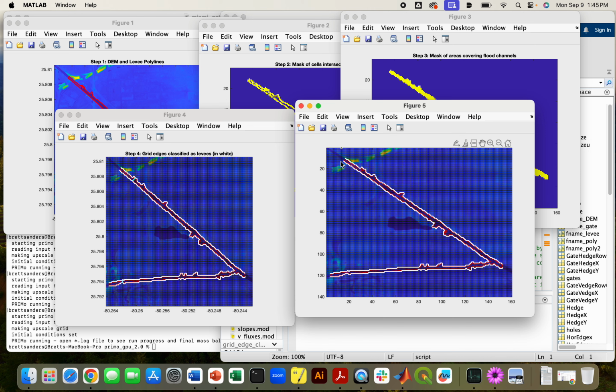And this numbering system corresponds to the conventions of numbering rows and columns in a raster grid, where the very upper left-hand corner is the beginning of the data set, and you work your way downwards. And that's in contrast with a conventional Cartesian coordinate system, which starts in the lower left and increases in the x direction and increases in the y direction this way.